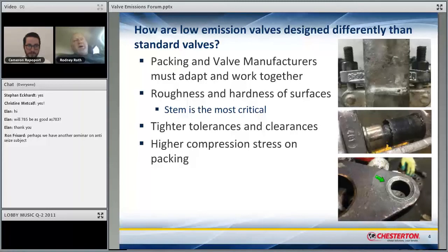Typically we don't see that embedment until we're repairing a valve, and people don't like to replace the glands. So we would just fix that by placing a hardened washer under the nut and lubricating effectively between the nut and hardened washer, and we wouldn't have a concern there any longer.